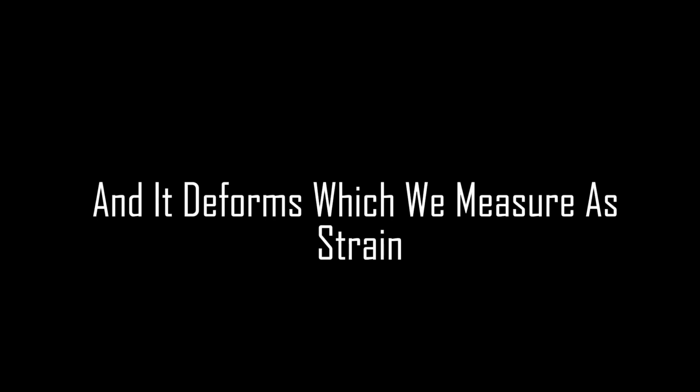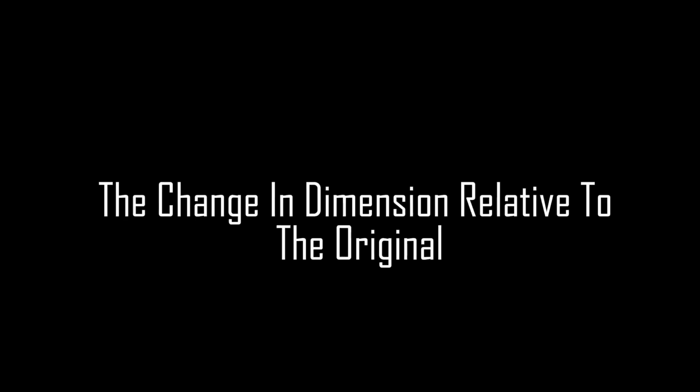Okay, structure, defects, strengthening. Now let's get practical. How do materials actually respond when we apply forces? Mechanical properties. Right. When you apply a force, the material experiences stress, that's force per unit area. And it deforms, which we measure as strain, the change in dimension relative to the original. And we can pull, push, twist. Yep. Figure 6.1 shows tension, pulling, compression, pushing, shear, sliding, torsion, twisting. The relationship between stress and strain is key. Like how stiff it is or how much it stretches before breaking.